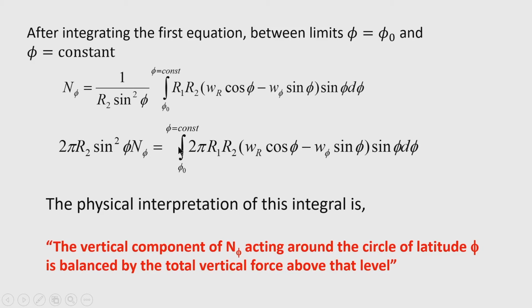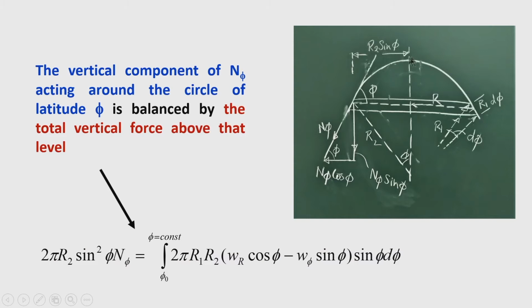Now, this term can be interpreted. When we see the shell surface under the action of load, and the meridional stress, that is n phi and n theta, developed in the meridional and circumferential directions, we can see that the vertical component of n phi is n phi sin phi.